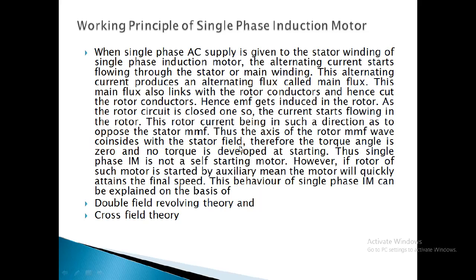Hence the fields created by the rotor and stator oppose each other. Therefore the torque angle is 0 and no torque is developed at starting in the case of a single phase induction motor. Thus the single phase induction motor is not a self-starting motor. However, if the rotor of such a motor is started by auxiliary means, the motor quickly attains the final speed.